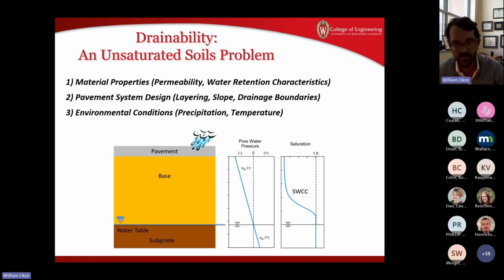You might hear that called capillary pressure. And so that is a water pressure that actually contributes to effective stress. And for some materials, not so much relatively coarse materials like the aggregates that we're looking at today, but for some materials, that increase in effective stress contributes to additional strength and stiffness of the system.